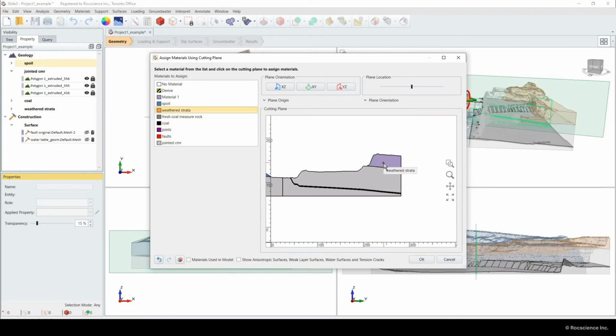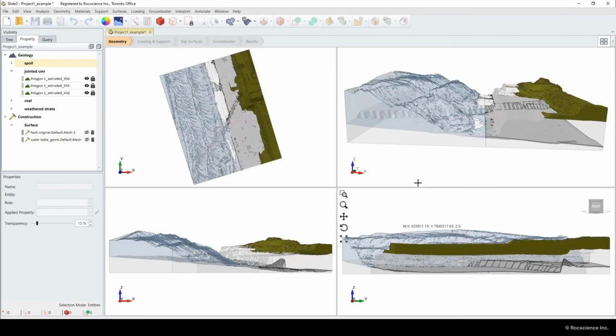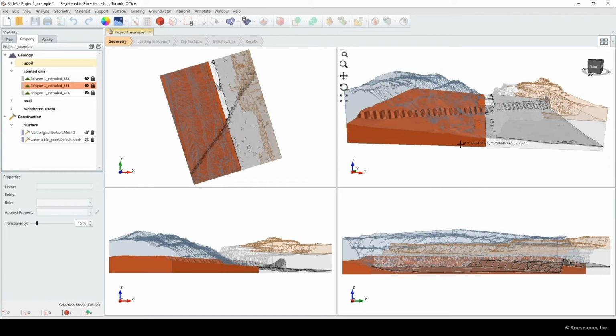You can see in Section View that I have two volumes of the same material that were created when I divided all using the manually inserted plane to create a volume for the D12 seam. To refine and reduce the number of entities in the model, we can select these volumes and union. This is an optional step.